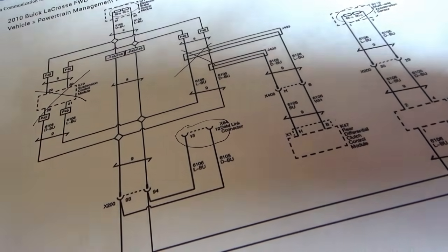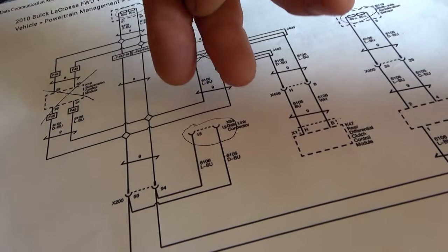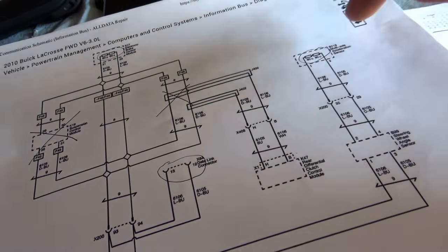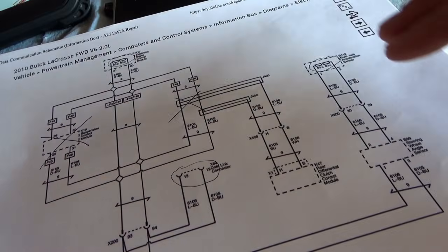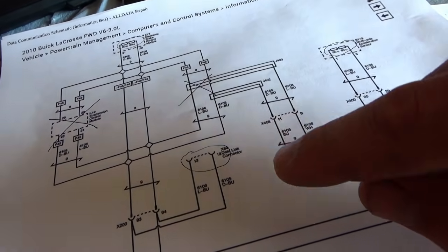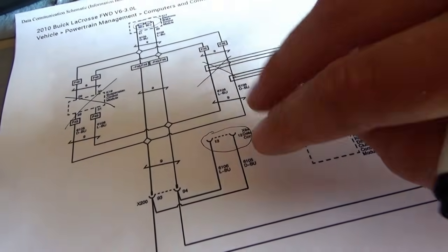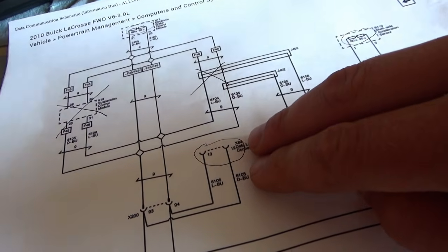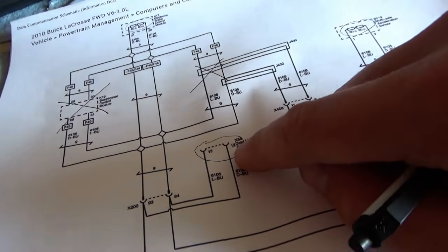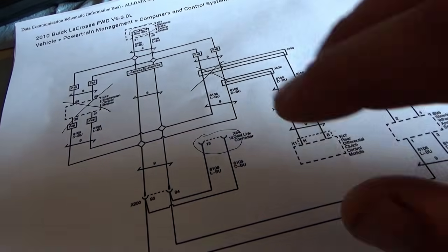So this is fantastic. This diagnosis shouldn't take too long because we have 3 modules and we have access at the DLC to measure these terminating resistors. I want to see, is this network sound? Are there any breaks in the wires? And is it shorted to ground? Is it shorted to power? What is going on? So we'll start with just an ohm meter and a voltmeter at the DLC without taking anything apart just yet, and see where this goes. So let's go to the car.